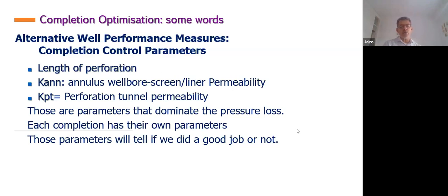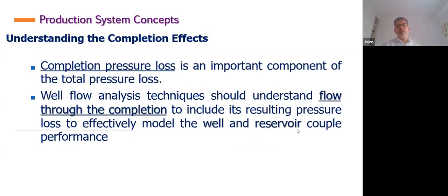Those parameters, like the length of perforation, define whether we did a good job or not. So completion pressure loss is an important component of the total pressure loss. Well flow analysis techniques should understand the flow through the completion, but nobody is considering that.